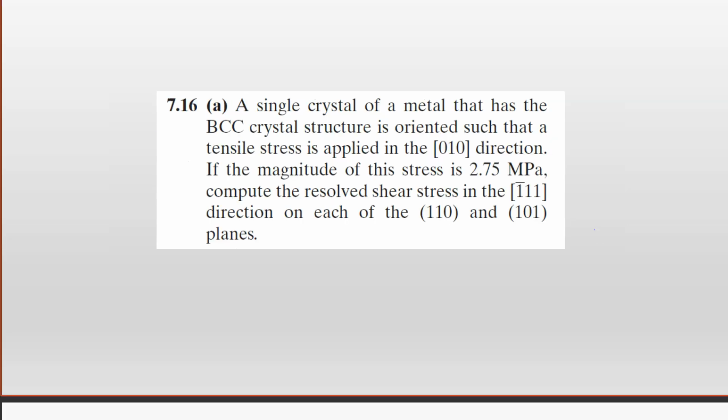Okay, let's apply this to this problem here. We have a single crystal of metal that has the BCC structure, oriented such that the tensile stress is applied in the 010 direction. If the magnitude of the stress is 2.75 megapascals, compute the resolved shear stress in the [1̄11] direction on each of the (110) and (101) planes.